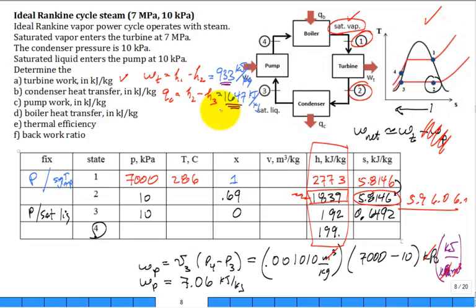Here it is, 933 going out where I want it to go, but 1647, a lot larger number, going out wasted, just dumping it to the atmosphere. Terrible. You engineers need to do better. But guess what this is? It's the ideal Rankine. This is pretty good. There's no friction in the turbine. Wait till you add friction in the turbine. Gets worse. All right. So let's keep going.